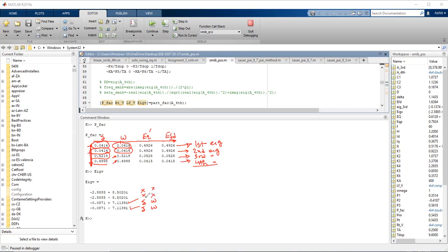Okay. So that means delta and omega, we have got 2 states and 2 eigenvalues. That means these two are related here, mostly participating. These 2 states are mostly participating in these 2 eigenvalues. That means this pair of eigenvalues is largely coupled with the delta and omega states. So the dominant eigenvalues are identified.